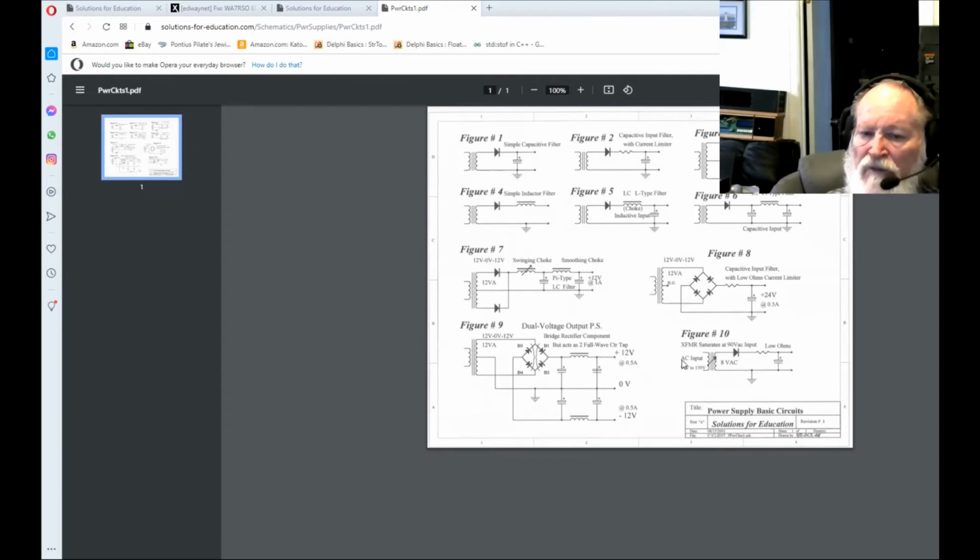Now take this diode out and take this capacitor out, so this becomes just an ordinary transformer. This might be 110 volts in, 110 volts out. But following the principle we were talking about up here, this one is designed so that when the line voltage gets up to around 95 volts, anything beyond 95 volts begins to taper off. You get full voltage, 110, coming off of this even when this is 95 volts. You have a few more turns here, so the turns ratio is a little higher. So with 95 volts here, you'd have 115 volts coming out.